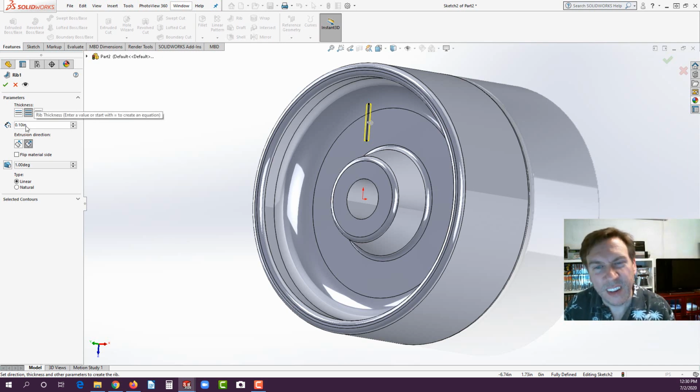Notice this, you can set it, we'll leave it at 0.1. Those of you who are taking this class are new to engineering. When you're dealing with plastics, remember there's a 60% rule. If your wall is 100 thousandths for most of the part, then you would want actually the ribs to be about 60 thousandths or less than. So we're going to just keep it at 0.1 because our walls are actually 0.25 thick. So we're in pretty good shape.